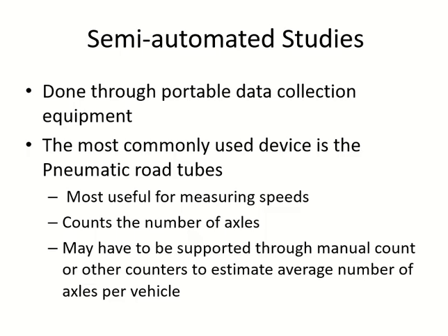So for semi-automated studies we use devices which you can carry, install on the road, and collect data without being there. When the study is done, we come back, take out the device and bring it to the office to get the data out of it. So you get the data of the study once you bring the device back to your office. This is what normally happens. The most commonly used type of portable device is a pneumatic road tube.